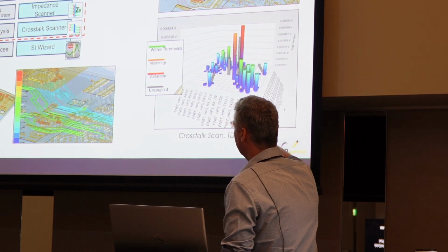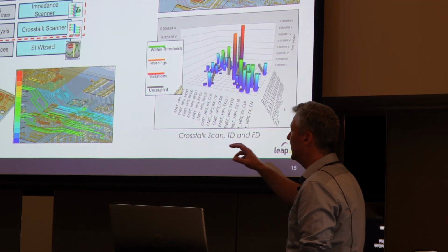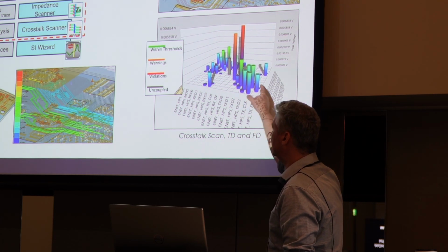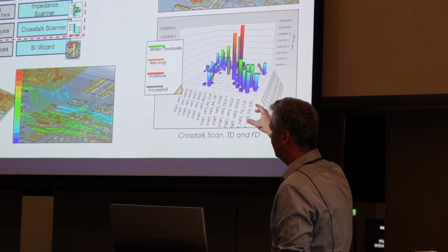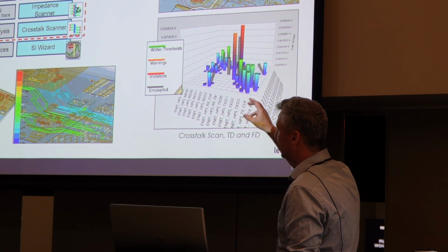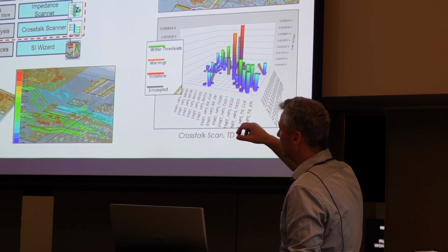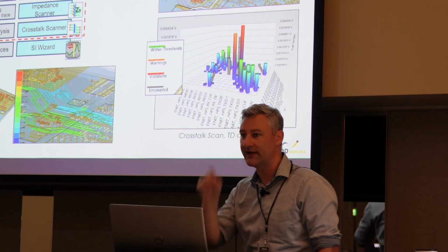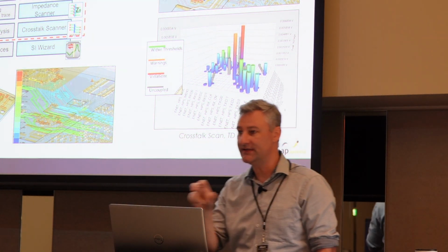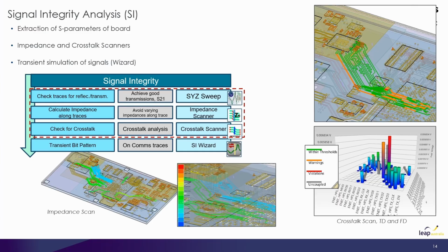plot here, where you put in violations before, and then you can easily see in a matrix-design type of plot where your violations and where your warnings are and where you are within your thresholds. Because you can then just pick one, and you can see directly where the crosstalk happens, or the unwanted crosstalk, and then you could change your design and move lines away.